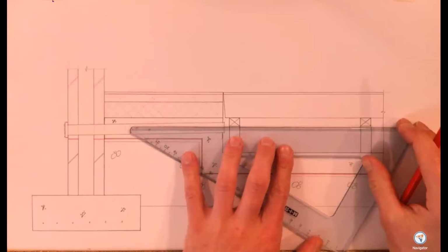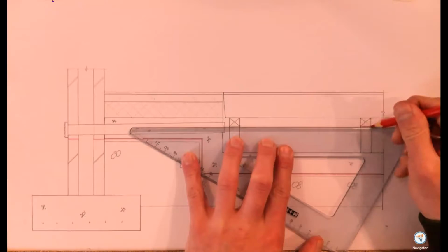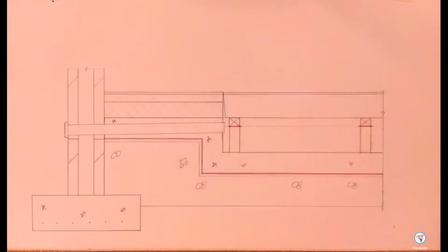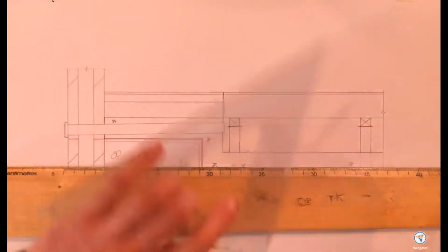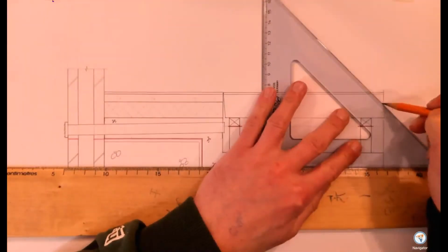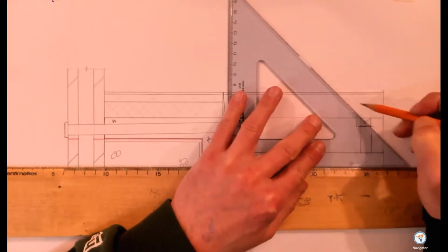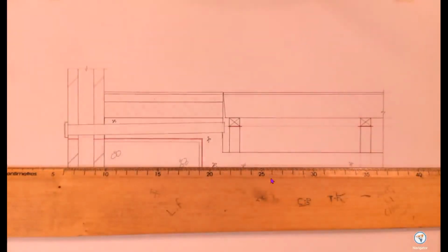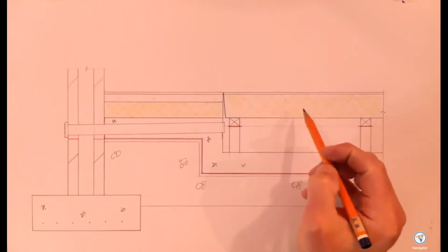So up top up here, they need to be dropped in. So damp-proof course here, damp-proof course in there. It said both floors are highly insulated. So what that means is that we need to put insulation in between the joists up here. And again, we'll use our PIR insulation. So I'm going to come along and put in my symbol for the PIR insulation, and I'll colour it in with a little bit of yellow. The PIR insulation is put in between the joists, so that's fixed in place.